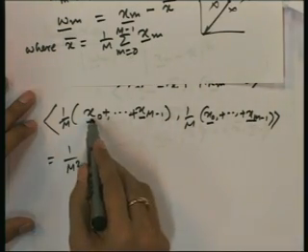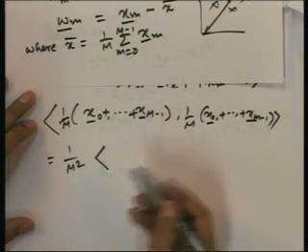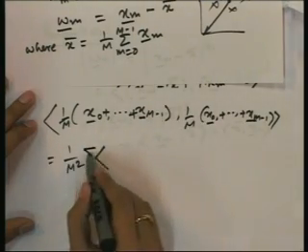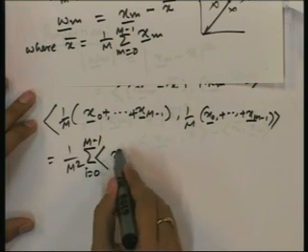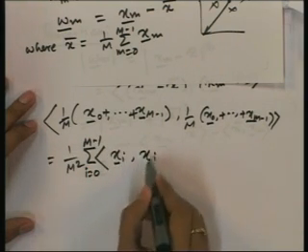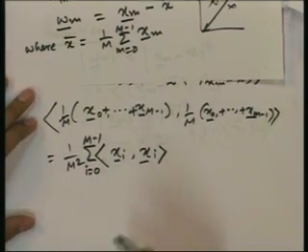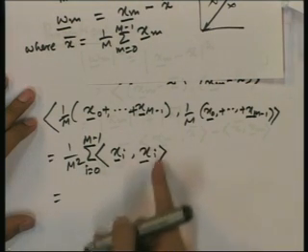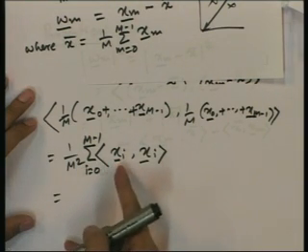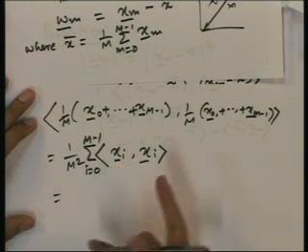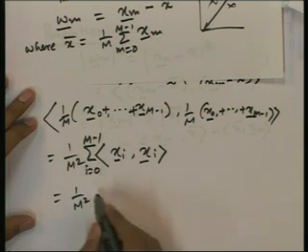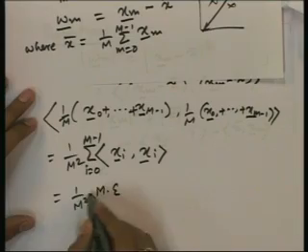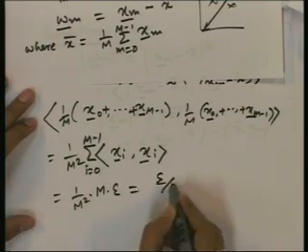So, we will have from i equal to 0 to m minus 1 only the inner product of xi with xi itself. All the cross inner products will be 0. This inner product we know is the energy of xi, so it is E. So, 1 by m square, there are m number of them, so m times E. So, this is E by m.